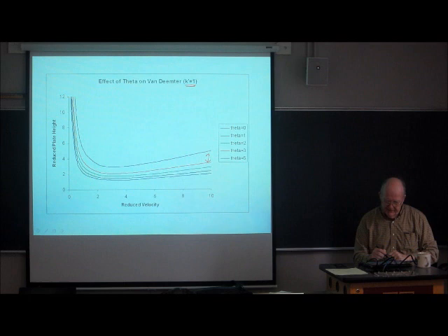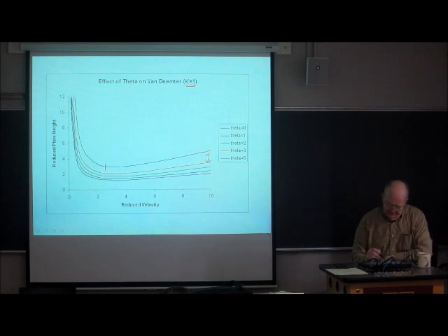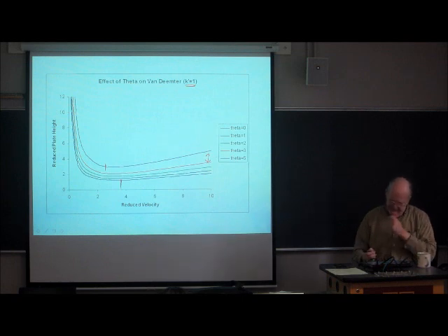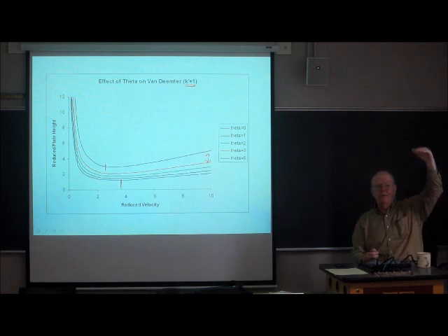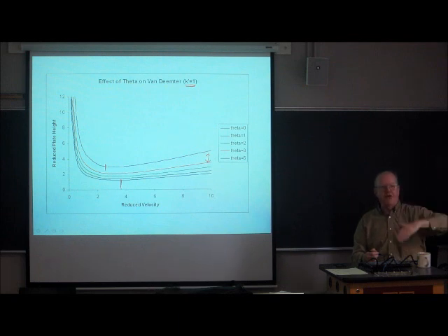It just continuously gets worse and worse and worse. If you look at the curves carefully, you'll see that the optimum is really shifting. And for the thick film, the optimum flow rate has shifted in. Here's the optimum flow rate with a theta of 0. And of course, the minimum HETP has gone up quite a bit. So clearly, you want a thin film.